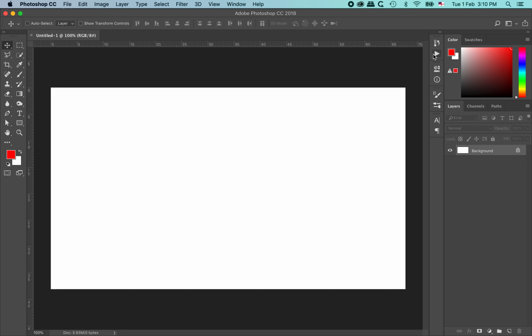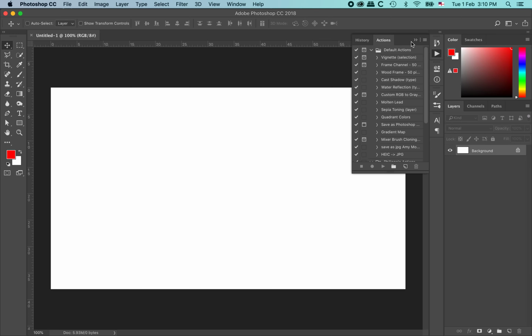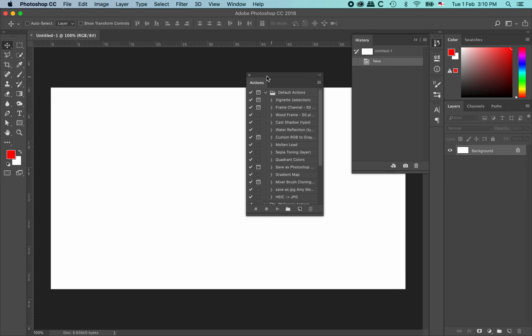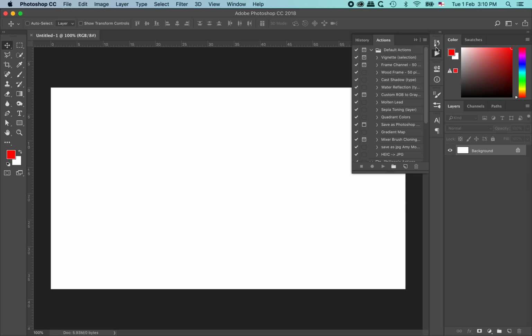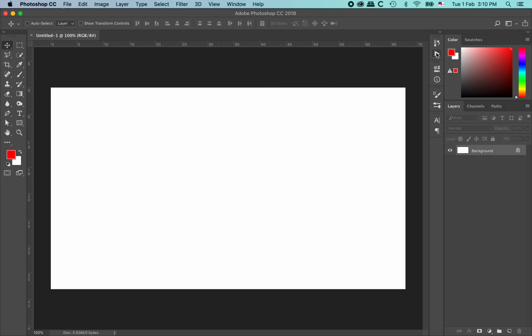And in between there will be these little buttons. Now the buttons will open further panels, so you can have panels small, or you can make them bigger, or you can rip them off and undock them, you can move them back and redock them. You can see I've got these two docked together now. So you can double click on a panel, clicking on the name, and it will make it smaller. So there's lots of different ways of reorganising your workspace so that you've got just the things that you need up and ready to work with.